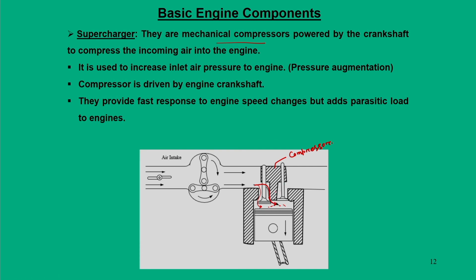It gives additional inlet air pressure to the engine, which we normally refer to as pressure augmentation. The advantage we get is a fast response to engine speed changes. Whenever we change the speed of the engine, it responds immediately, because we have a supercharger.